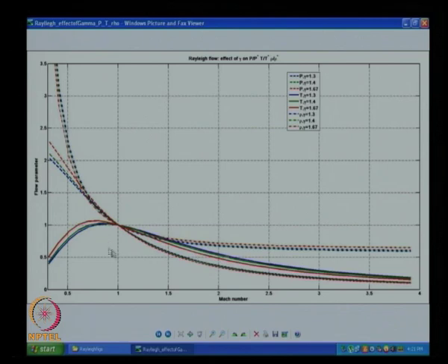Now, we will look at details. If I look at any one of these curves, let us say I will pick pressure, the dashed line here. Pressure is coming very slowly changing towards m equal to 1, and remember that my flow always ends at m equal to 1 if I am heating the gas. If I am heating a subsonic gas, the pressure drops because it is accelerating towards m equal to 1. If I am heating a supersonic gas, the bottom one happens to be the dashed line and this one happens to be for density. It is supposed to be dash dot line. The dots are not very clear on screen.